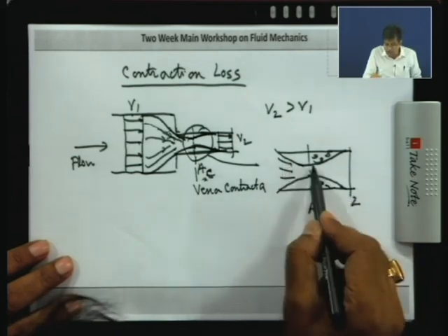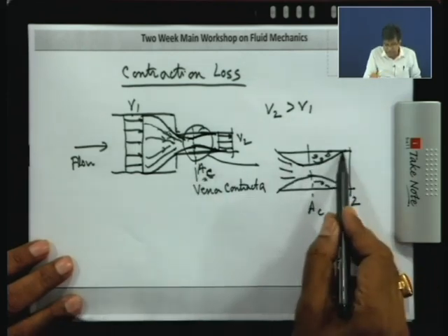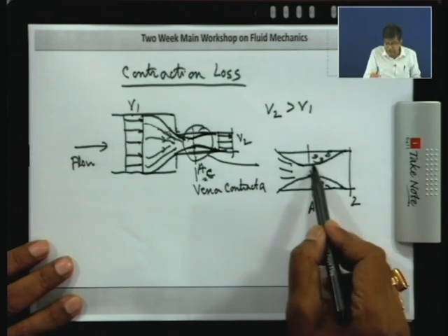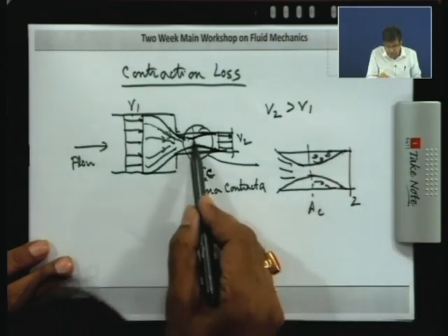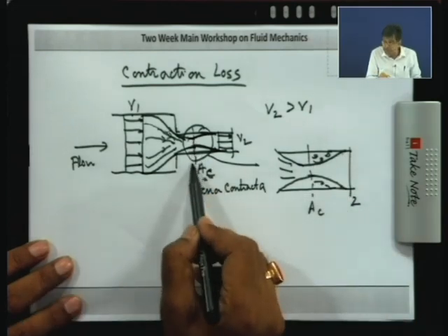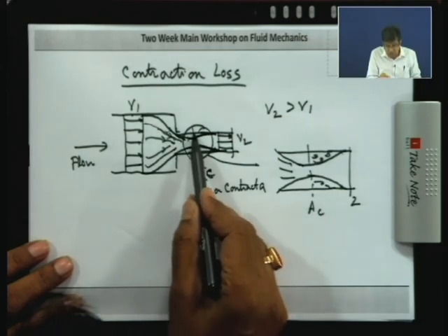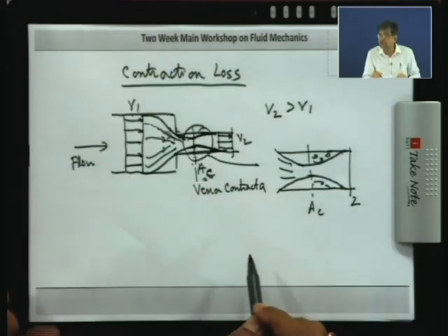It is not due to contraction, but why expansion followed by the contraction? Expansion is needed. This is because the stream tube attains a minimum cross sectional area which is lower than the area of the tube.